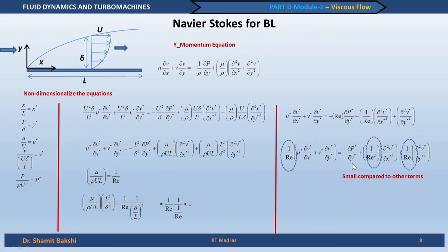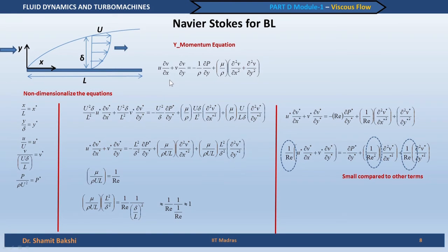So, that is basically the advantage of using dimensional analysis or writing the equation in a non-dimensional form. If you do that, then you can see which terms will play a more important role in an equation, and you can reduce it into a more simplified form, and you can solve it easily. So, for example, in this particular case you will see it becomes very simple. We began with this entire equation, which is very difficult to solve, but just by non-dimensionalizing this equation, what we got is that for high R e, del p by del y is equal to 0 is the equation you have to solve, which is very easy to solve of course.